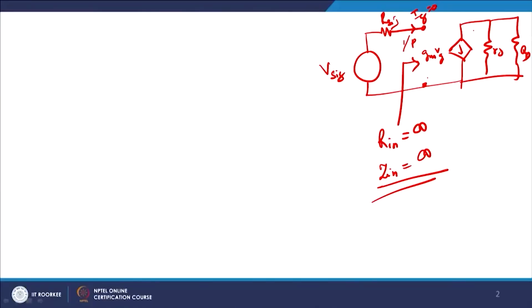This oxide layer is a dielectric material, of course, and therefore I would not expect any current flowing through the MOS device as a gate current. Looking from the gate side, which is the input side, your impedance will be very large. So, your Zin will ideally be infinity, so large, and therefore I keep the input side open.